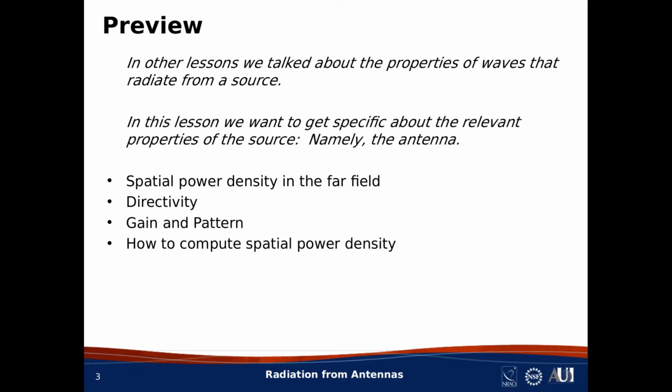Then I'll introduce the concept of directivity, which is a handy description of how a particular antenna distributes the power that it radiates into the far field. This will lead to the concept of gain, which is simply directivity corrected for loss, and pattern, which is simply directivity expressed as a function of direction. Finally, I'll show you how to compute the spatial power density radiated by an antenna at any distance and in any direction, and all we'll need to know is the transmit power and the gain.